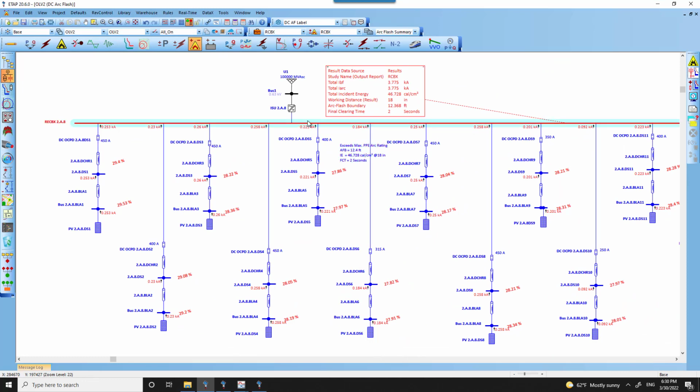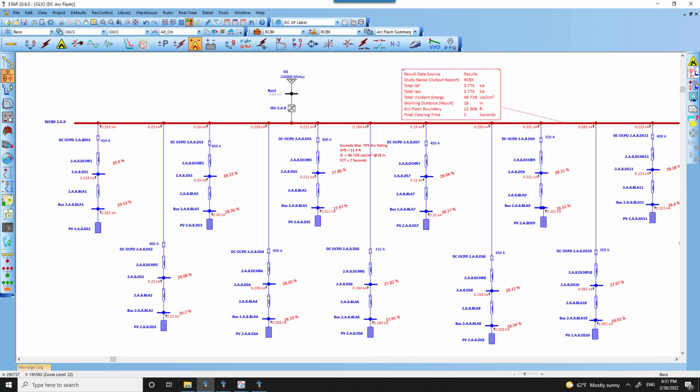And so the scope of the study had PV arrays that are actually connected to the inverter combiner box, and that combiner box would in turn give us the connection to the actual AC side of it that goes to the actual facility at the 34.5 kV switchgears. So in this case, we had two locations of interest. One was the recombiner box, which could basically calculate the incident energy at the 2-second rule, assuming all the particular PV arrays were contributing to the fault as a worst case.